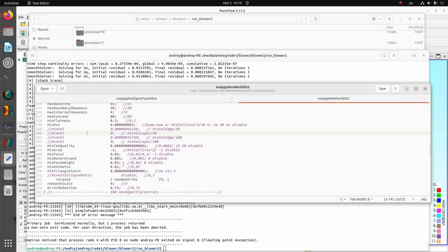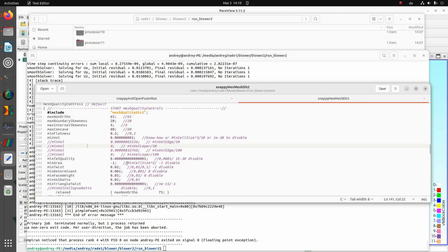So in order to do a normal calculation, we have to change the mesh wall settings. For that I go to dynamicMeshDict and activate the mesh wall definitions, where we have the definition of mean cell volume divided by 50.